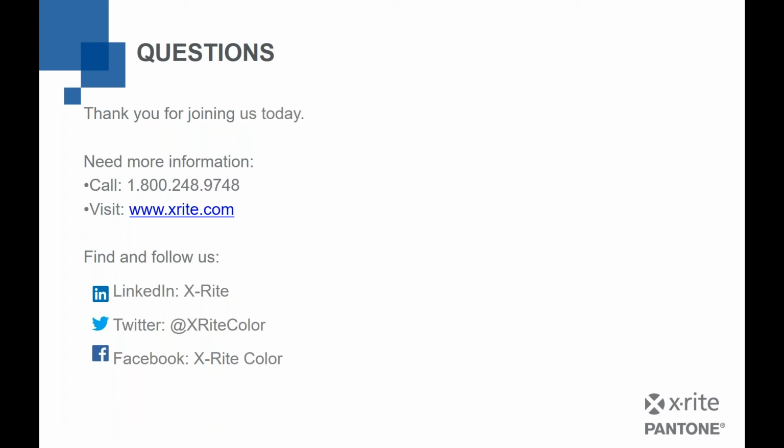One other question I see here: what about viewing the sample straight up and down and not at an angle? That's a problem relative to the way that the light is hanging. In a booth, the light is perpendicular, shining straight down onto the table or the work surface. If I stand my sample up, I'm going to see a lot of gloss, because the light's coming straight down and running perpendicular to the sample instead of actually shining on it. So we would not recommend that as a method.